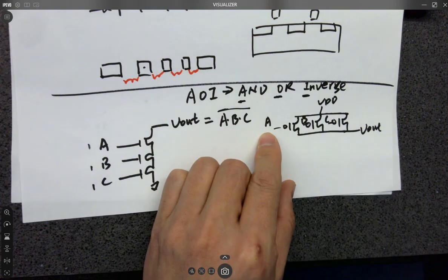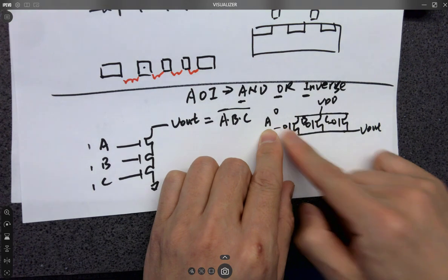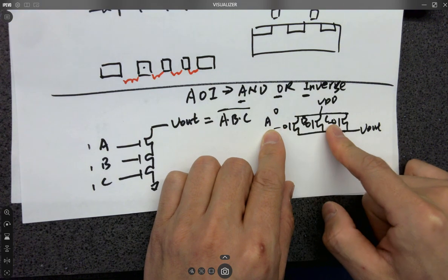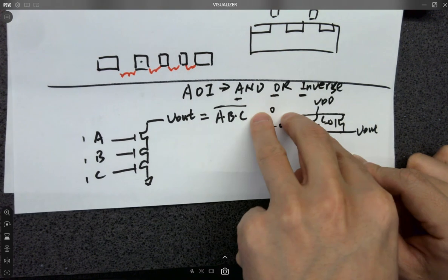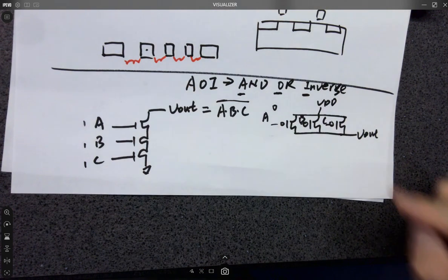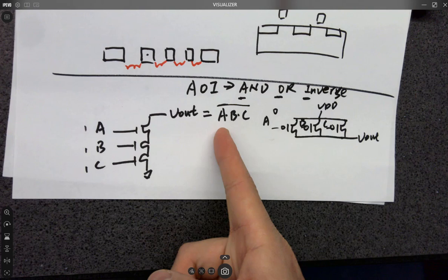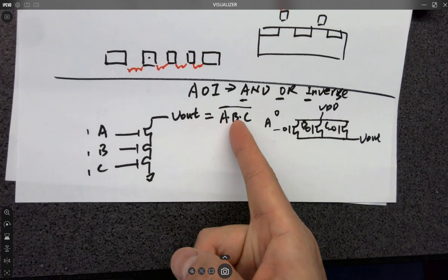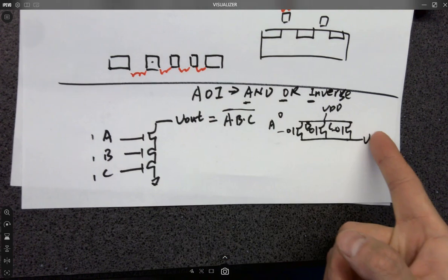so you need a voltage 0, right? You need a 0 to turn on the PMOS, right? It could be this one becomes 0, this one becomes 0, this one becomes 0 as well. Doesn't matter. Or 2 zeros, or 3 zeros. Doesn't matter. It's still the same logic. Take a look. You just need one of them becomes 0, and the whole thing becomes 0, and then you invert it, and it becomes 1.